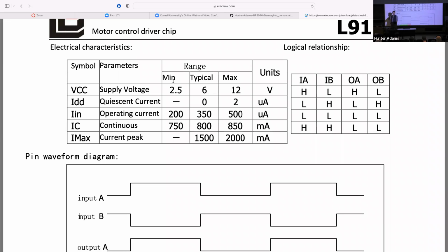This integrated circuit will protect you from yourself. If on this integrated circuit you make both the inputs high, the consequence is the motor just brakes. The output's low. I'm pointing this out because this can introduce a bug. Suppose you're testing the two PWM output channels, and just to test things, you have very reasonably said, I'm just going to set both the PWMs to the same duty cycle, same waveform.